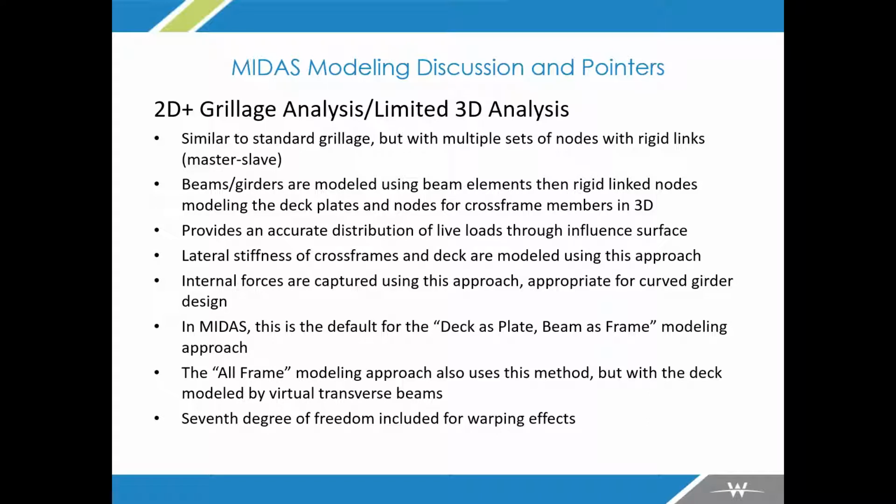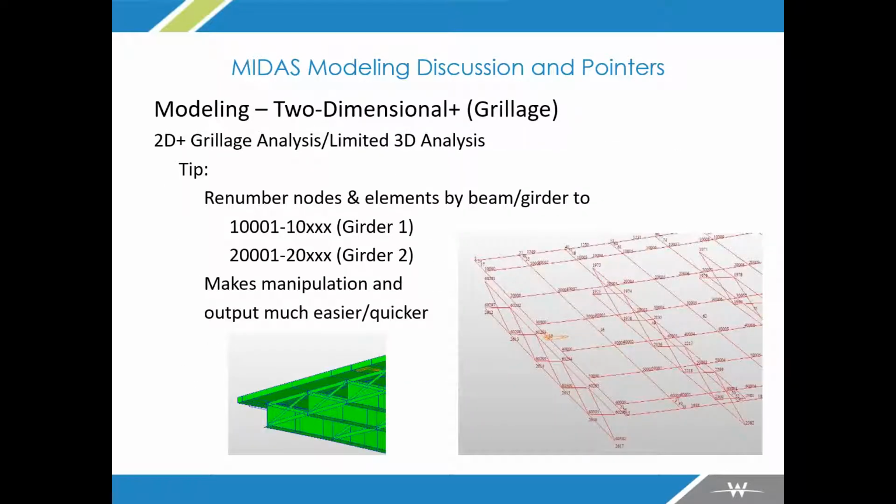It does increase run times. Also, the all frame is not as automated in terms of being able to extract rating factors directly out of that. MIDAS is really set up more for the deck as plate, beam as frame when you get to the back end of it, trying to extract that stuff out. So that's the one I would most often recommend unless you have something very unusual. And here's kind of what that looks like.